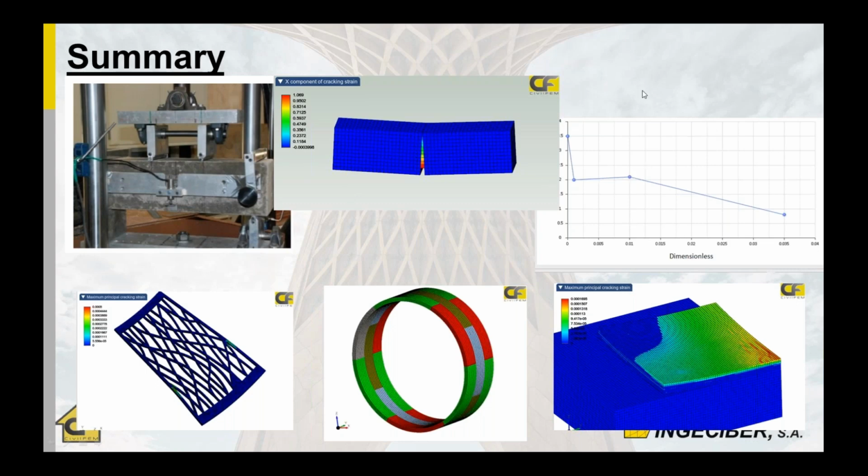And once you have selected the properties you would like to input, you can input them in any type of model, model it with solid elements, and perform nonlinear analysis, applying the load combinations you have for a building, with extra loads, and then increase those load combinations until the collapse of the structure. So you obtain safety factors for the first crack and for the collapse of the structure.